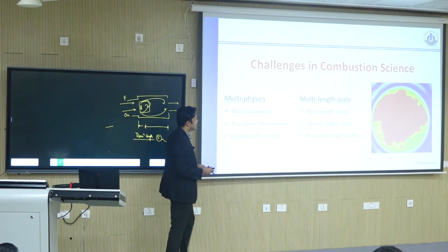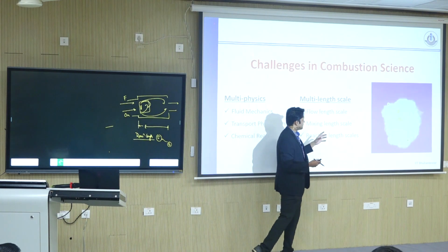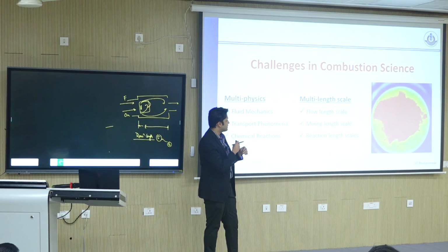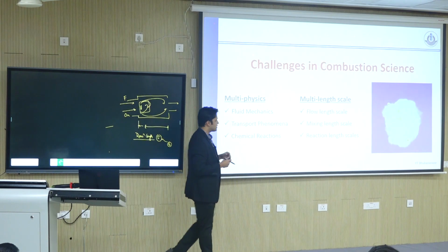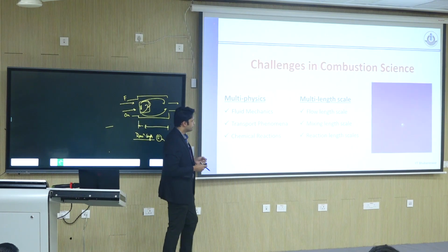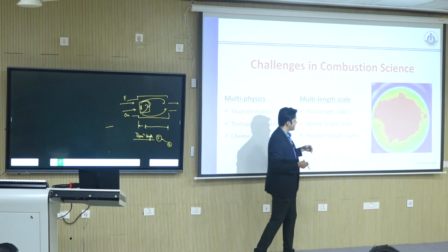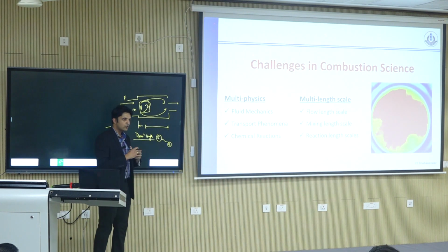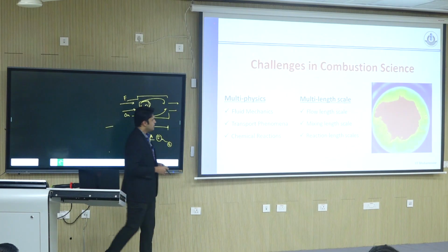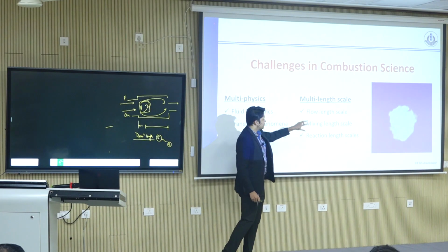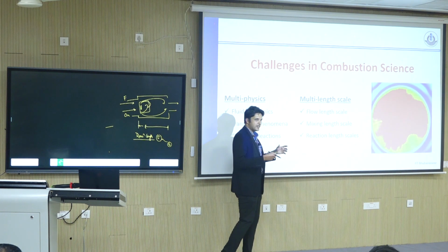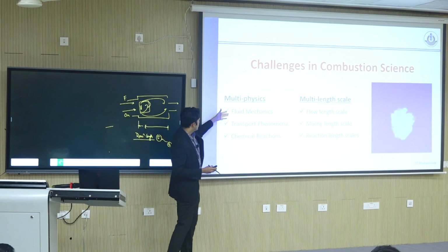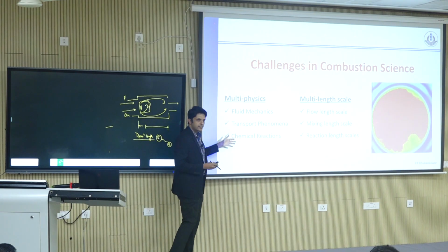So you can see this kind of flame propagation. Again, this is not a very nice flame, so you can see the turbulence and it is propagating in a random manner, right? This is a turbulent flame propagation that you see. These are taken with high-speed cameras so that you can characterize how the flame is growing. To understand these concepts and to engineer devices where you can control combustion, you have to have a good idea about these three aspects.